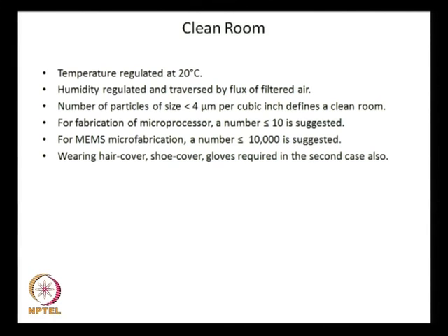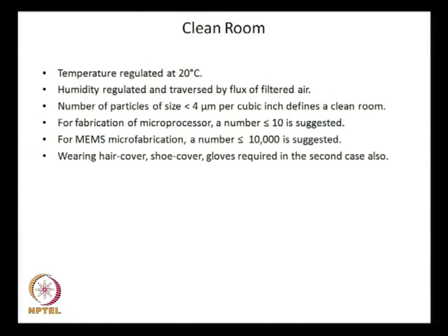So, what this means is that the clean room required for microfabrication of a MEMS device may not have to be the same as the clean room required for fabrication of a microprocessor, and still for a MEMS device you need certain cleanliness, and that requirement is here: wearing hair cover, shoe cover, gloves etc., and of course, the other conditions have to be satisfied.